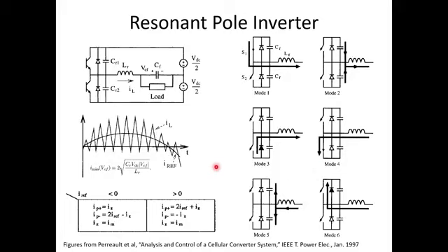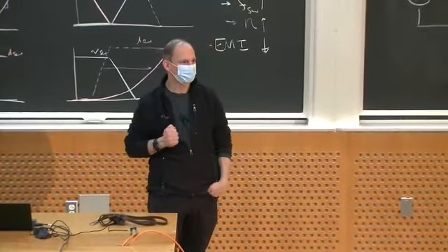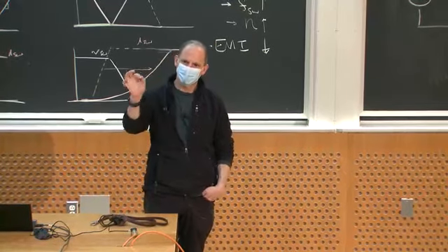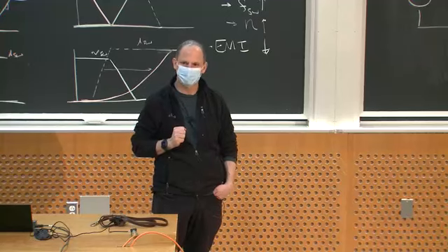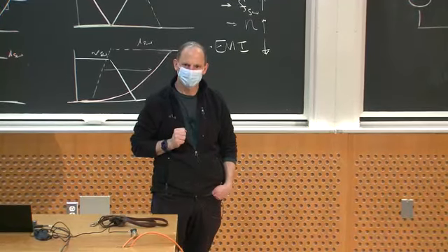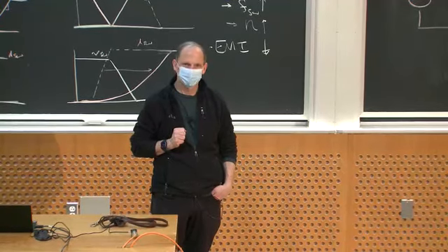So usually when you look at this kind of circuit, you say, okay, when the device is turning off, it's loaded by some impedance that typically looks inductive, or basically is carrying a current in a direction that will help charge those capacitances in the right direction to give you soft switching. That's the way to think about it. Questions?